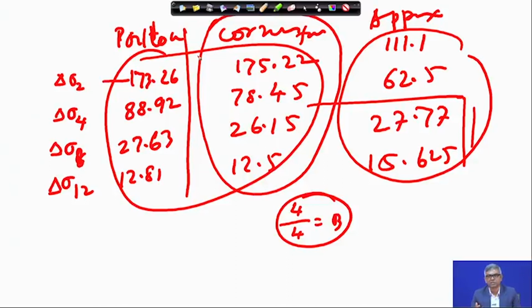Sometimes people use charts, which I have not shown here obviously. If you see any book, you will see a number of charts given with m versus n and the influence factor I q, which can also be used. Otherwise, in exam calculations most of the time we do not expect the corner formula, we generally use either the approximate or the point load formula. Otherwise, anything can be used. If you want to get an accurate value, obviously the corner formula is preferred, but you have to do a lot of calculation.